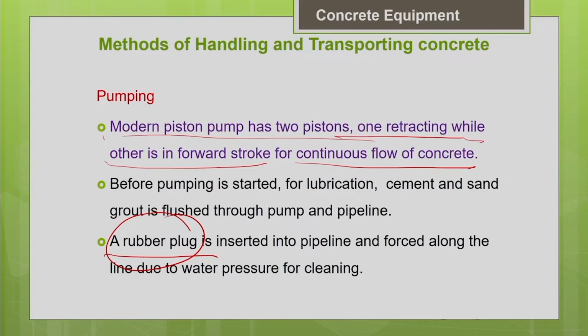If you need a steady supply of concrete, in that case pumping will be easier. Otherwise, if you need concrete in an intermittent manner, this process will be very tedious, because every time I have to lubricate and clean it. So more effort is involved in that. For a steady supply of concrete, pumping is the best option.